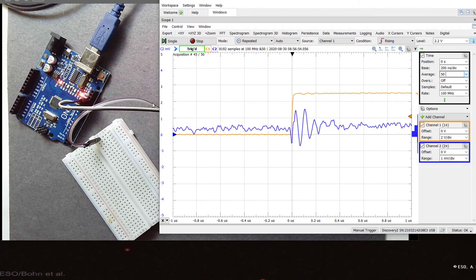And it also says whenever we're measuring low-level signals, we always want to be careful of how much of that noise that we're seeing, the synchronous noise that we're seeing, how much of that is due to an artifact of the measurement system versus an actual measurement on the device under test. This is going to be an important consistency test that we're always going to want to think about doing whenever we look at low-level synchronous noise.